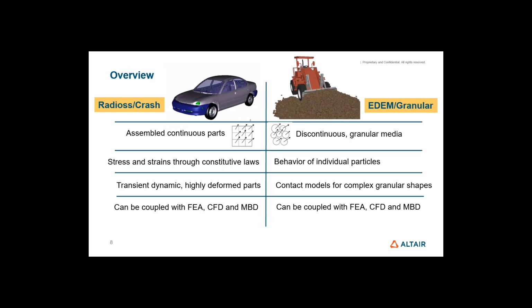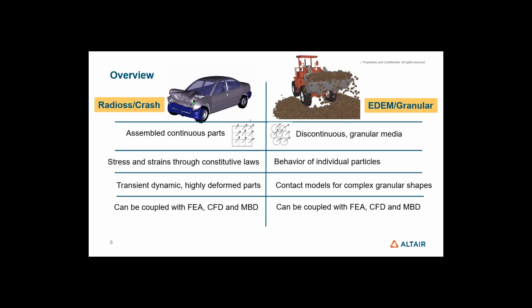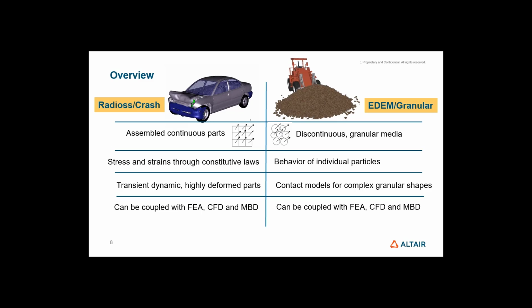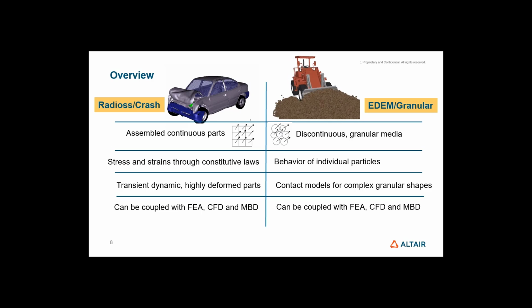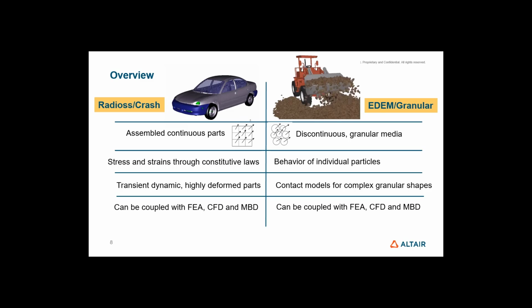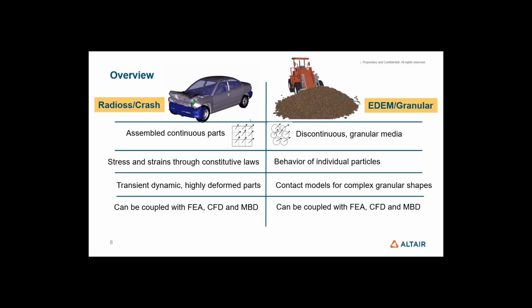And this is, for a crash, a transient dynamic problem because it's a very time-dependent problem, and the structure is deformed highly. One advantage of Radioss is the fact that we can couple it with other kinds of computational methods, other kinds of finite element analysis, CFD analysis for computational fluid dynamics, and multi-body systems.